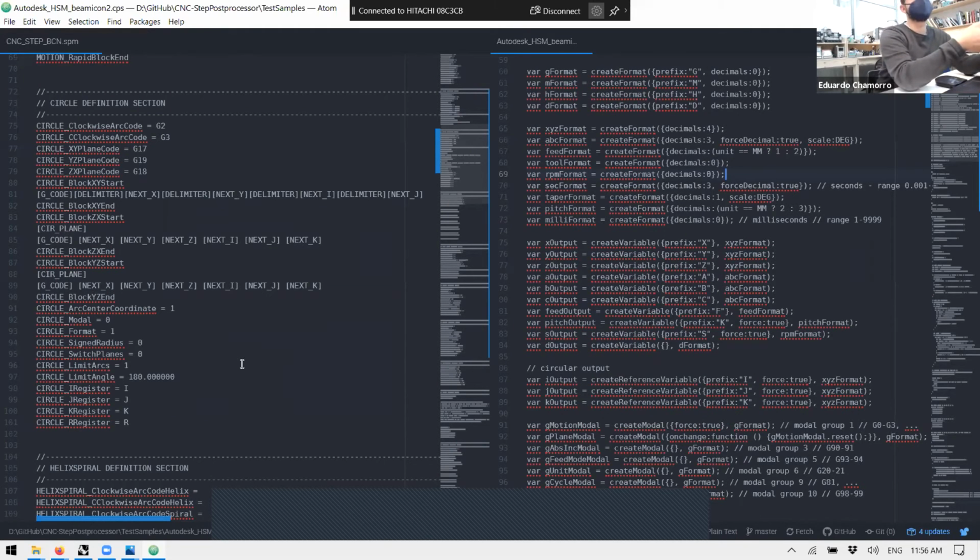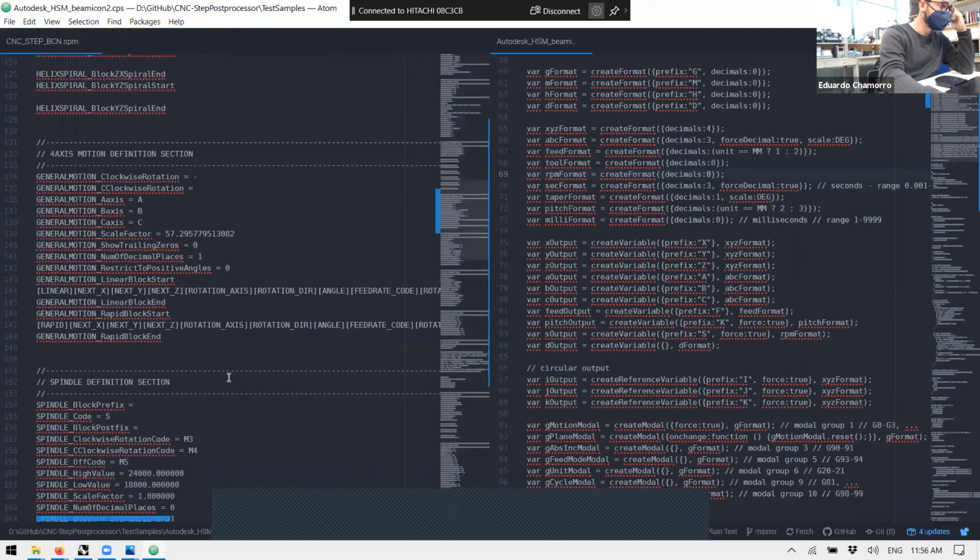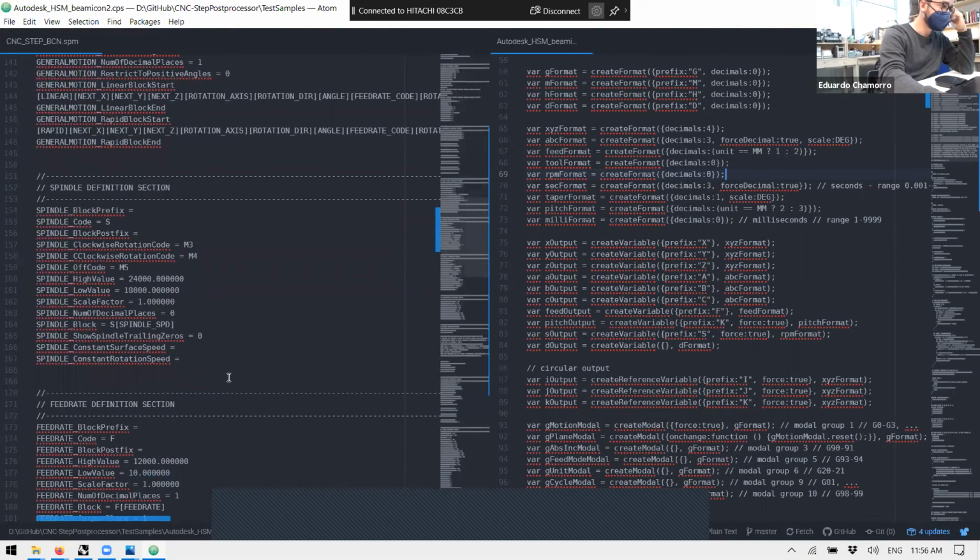After writing this post processor, we run a lot of tests on the machine, like making different shapes and three-dimensional millings, checking accuracy with calipers and measuring the tool on the outcomes to see if the file is exactly as the outcome. We didn't just create the post processor and hope that it's working.